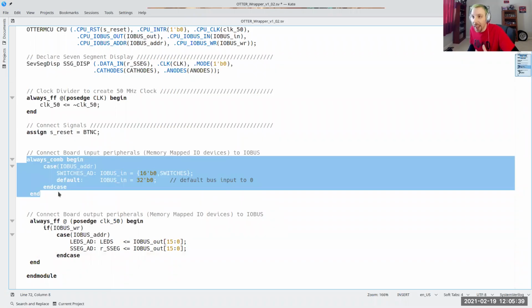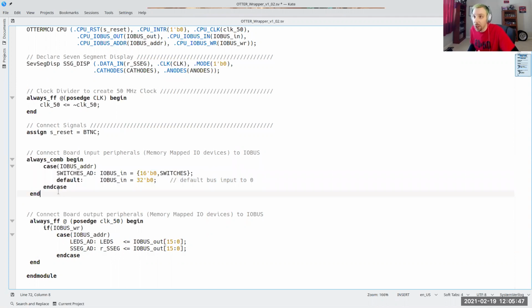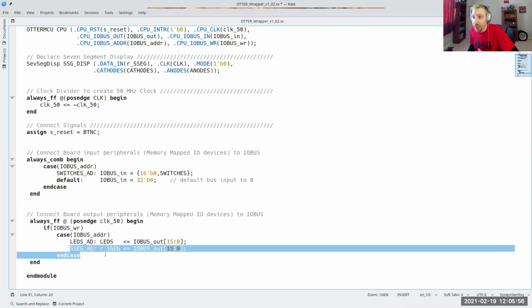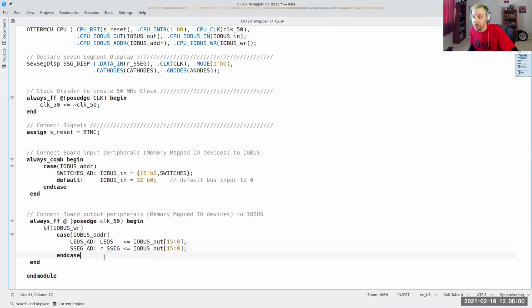Combinational logic has no save state. And so if you define one, it's going to create a latch, which is going to be bad. So always have an else, always have a default for combinational logic. I don't need a default for sequential. Questions on that?